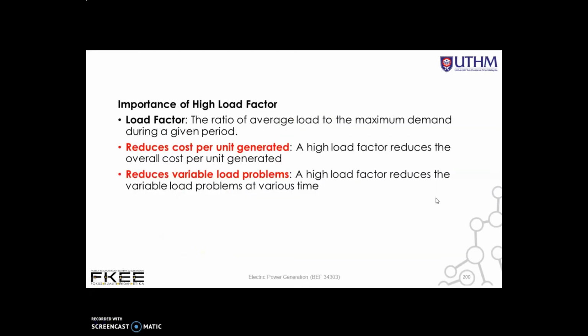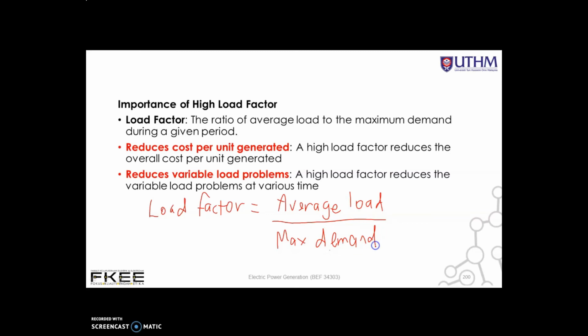Okay, in economics of power generation, it is important to ensure a high load factor. So what is load factor? Load factor is the ratio of average load divided by the maximum demand. That is called load factor.